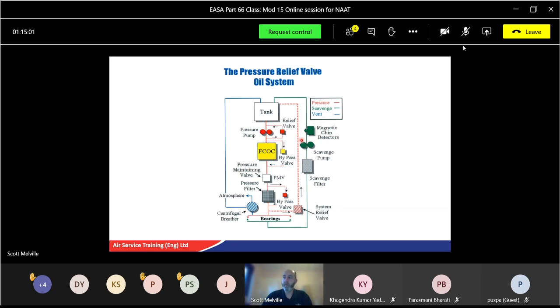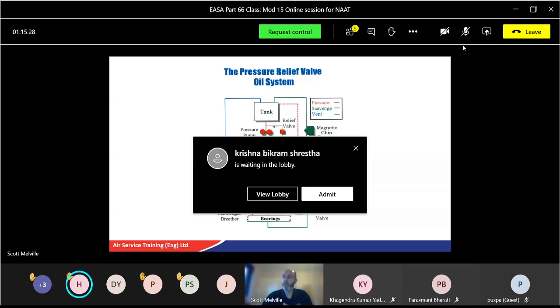So that's just a very basic oil system for a pressure relief. Now it's classed, as I say, as fully recirculatory. In other words, the oil goes in, it goes round, and then it comes back again. So it's keeping the same oil. Yes, you will lose a little bit through atmosphere, but that's just natural. But it's classed as a fully recirculated oil level, and you just have to keep topping this up every so often. And again with the pumps, small pump, high pressure, large pump for the return.